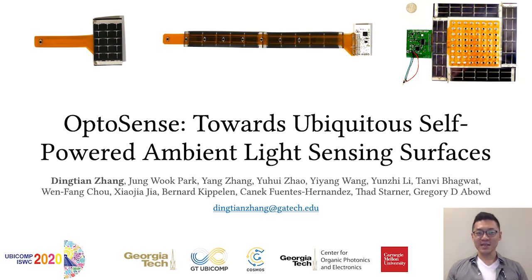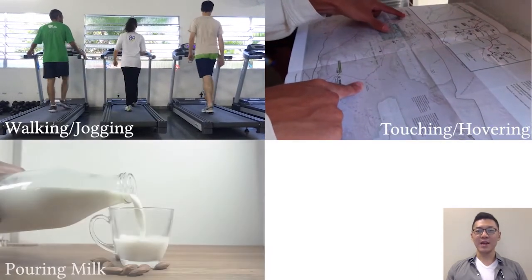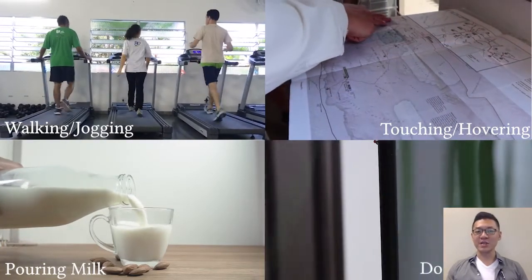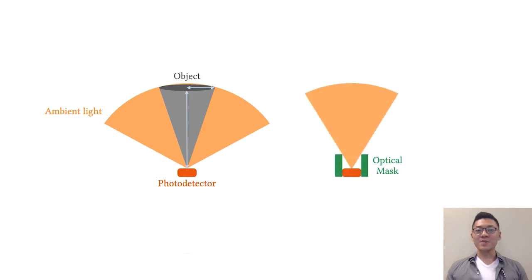Human activities, directly or indirectly, block the path of ambient light incident upon surfaces of everyday objects, creating interference patterns that can be captured by photodetectors on these surfaces. A photodetector can detect the presence of an object through changes of ambient light intensity. The detection is affected by the size, distance, and opacity of the object. An optical mask that restricts the field of view of a photodetector can tune its detection range.